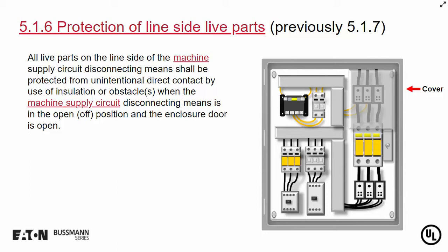Just keep in mind here, we're talking about protection from electrical shock. In this particular example here, you still have an arc flash hazard with that disconnecting means open, because you still have live electrical parts inside that enclosure. So we need to be cognizant of the difference between protection from electric shock as opposed to protection from the arc flash hazard.